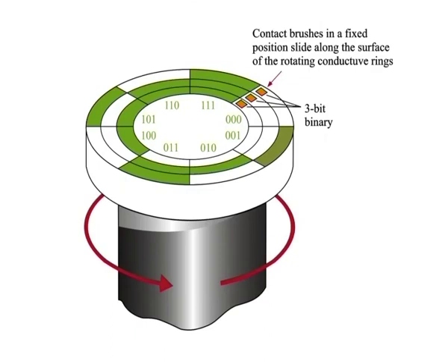In this type of application, it is virtually impossible to maintain precise mechanical alignment of all the brushes. Therefore, some error will always occur at many of the transitions between sectors. The gray code is used to eliminate the error problem which is inherent in the binary code.